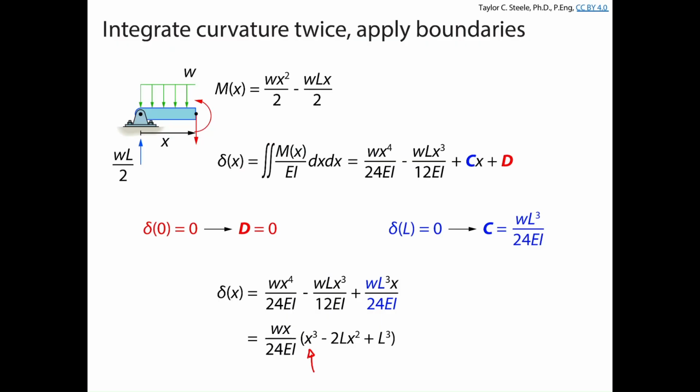So if I want my maximum deflection, I can just say x is equal to L over 2. I can plug that into this equation, and what I'm going to get is 5 W L to the 4th over 384 EI. Right, so that's an equation I talked about in assignment 0. Does everyone remember that equation? You must have talked about it in either structural analysis or mechanics and materials.